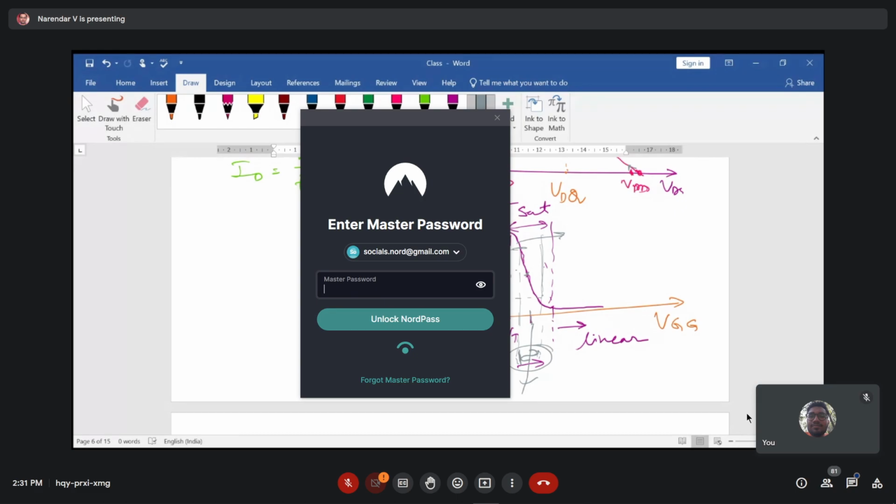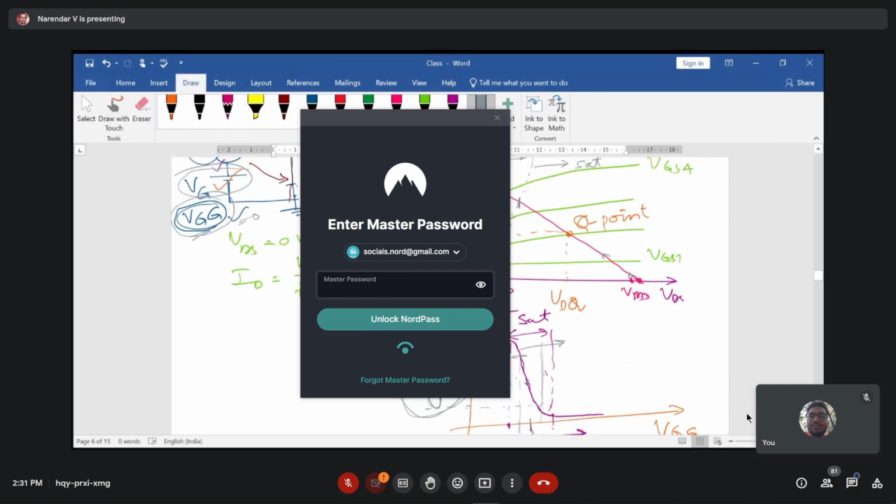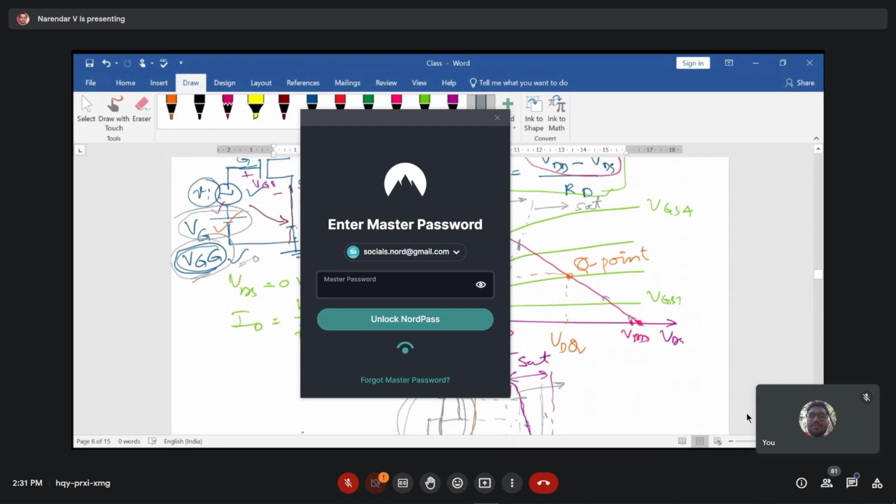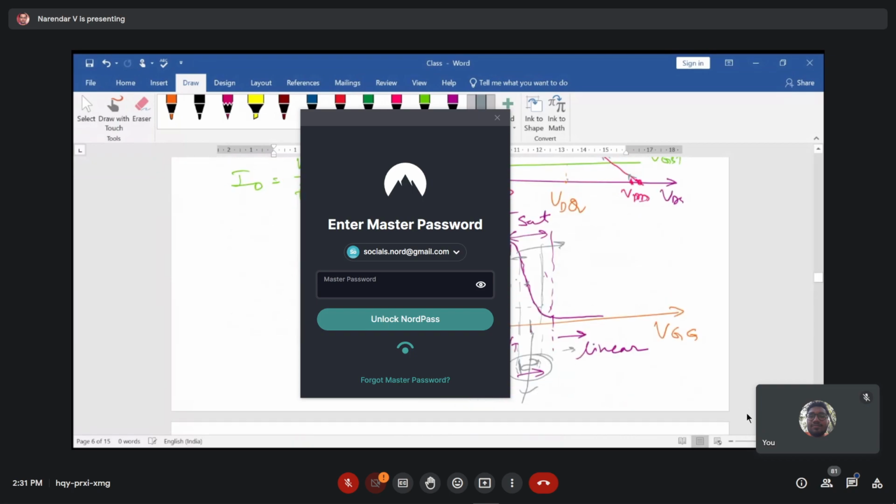Sorry, here we are talking about only the voltages. As you are increasing the voltages, the corresponding output voltage variation shows a maximum in amplitude, right? So while fixing the value of your VGG, you need to fix a Q point, and that should be greater than the threshold voltage of the transistor. If it is less than the threshold voltage, then there is no amplification in our transistor, because the transistor itself is off, because it is in the cutoff region of operation.